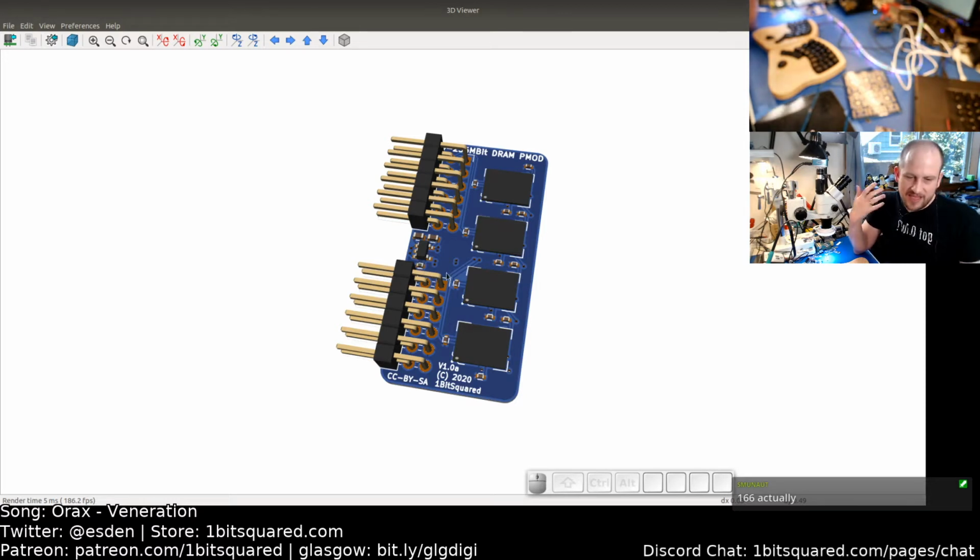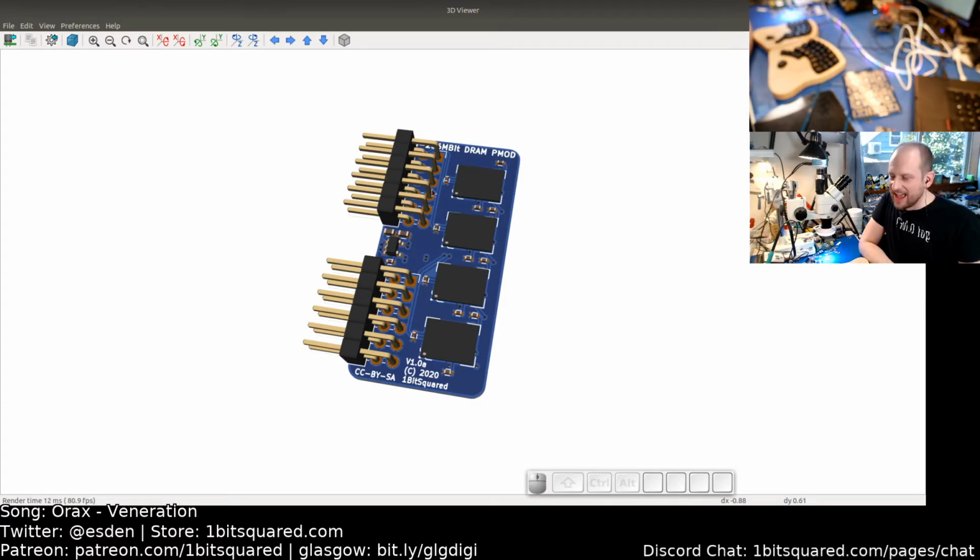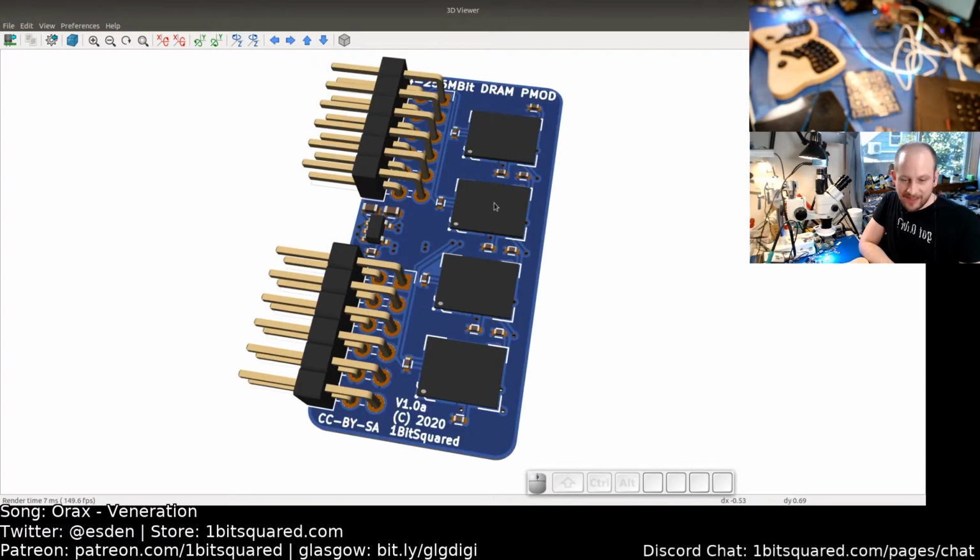That's an easier solution in a sense. And I'm not even talking about just the Icebreaker. Other FPGA development boards have similar issues where changing the I/O voltage is easier than changing the power supply voltage on the Pmod.